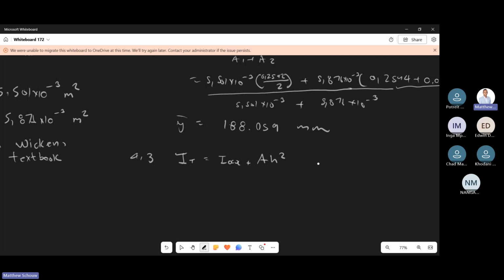So we'll be using this formula for both the I-beam and the channel. And then basically what we're gonna do is add both of them up, right? So we do one for the I-beam, one for the channel, and then we add them up. So for element 1, I want us to get the IXX value from the table. For the channel, what is the IXX value? This is the resistance to bending I was talking about, right? Can you quickly go check for the I-beam? What's IXX?